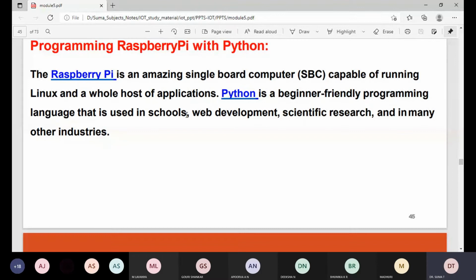For the description, we can look at an example of controlling the state of LEDs from on to off state or vice versa from Raspberry Pi. The schematic diagram of connecting LEDs to Raspberry Pi shows how to turn the LED on or off by running the code given. In this example, the LEDs are connected to GPIO pins 17 and 27 respectively, which are initialized as output pins.